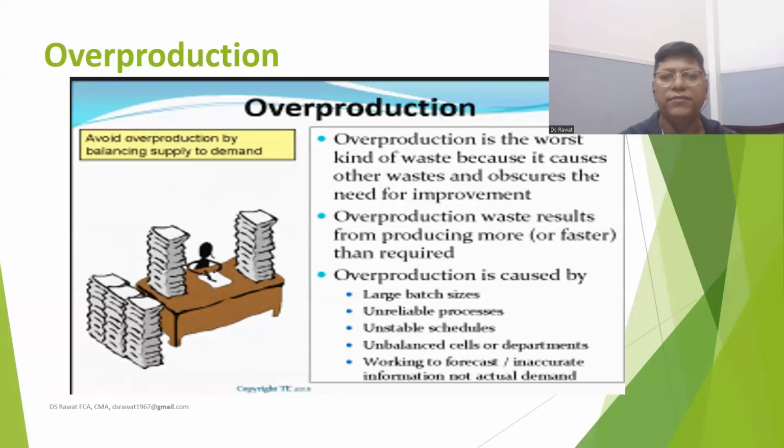Then what should be the strategy? The strategy should be to combine the orders of similar types of customers and come to the optimum size. Suppose there are two orders of 30 metric ton and 30 metric ton, making 60 metric ton. Then instead of taking separate runs for 30 and 30 and producing 20 metric ton waste, we can run a single batch of 60 metric ton, because the batch quantity is higher than 40 metric ton. This is called combining the orders in production planning.